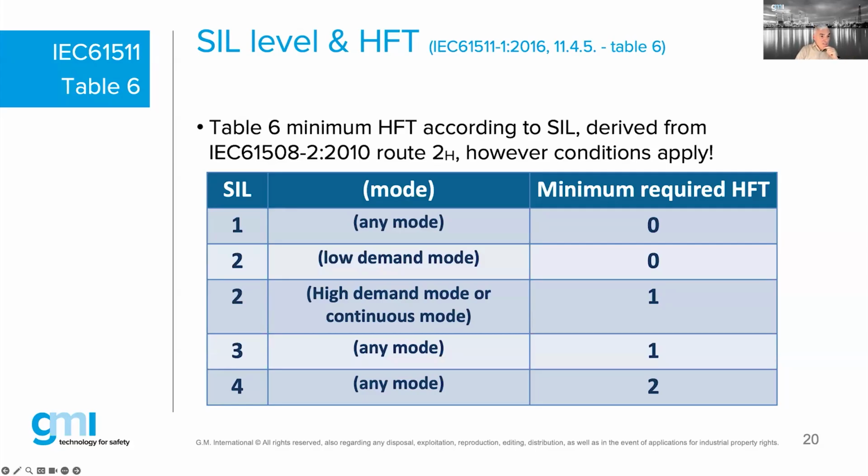What is the difference between SIL determination and SIL verification? That's actually a good question. That all depends on how you understand SIL determination. When you determine a SIL, it's based on the target SIL you try to achieve. When you verify a SIL, it is actually evidence to prove that the equipment you will use in your safety loops meets it, by means of calculation on availability. That is called a verification. The other one is called the determination. All right. So we answered that in 1 minute, 4 questions. I bet you if you would ask ChatGPT, it's faster, but not necessarily correct.